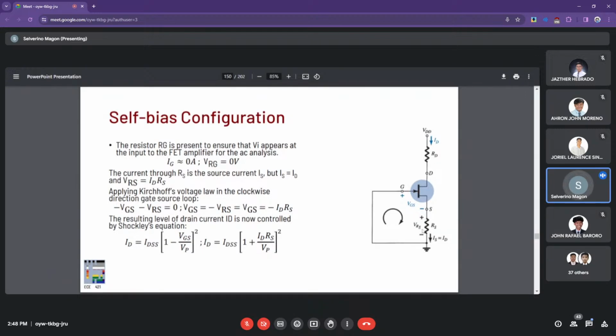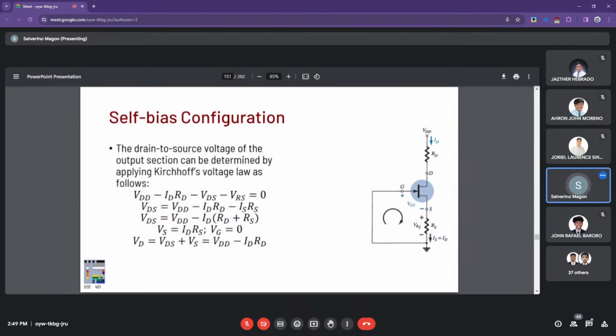RS is provided by your design. Now you have two sets of ID values in this equation, and it's second degree. So we can calculate this using the quadratic formula if that suits you, or on calculators, just do a shift solve and we're good. Once we can come up with the ID values.